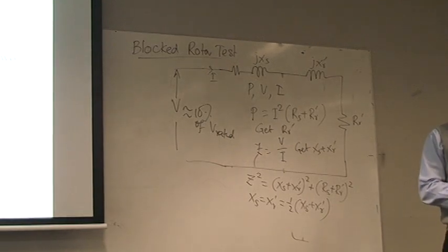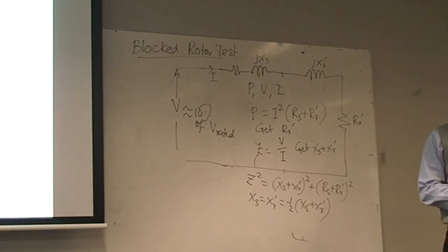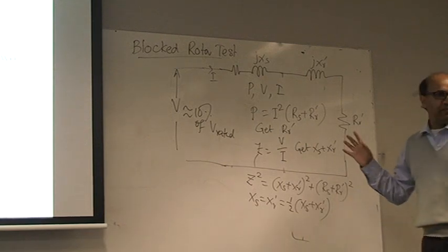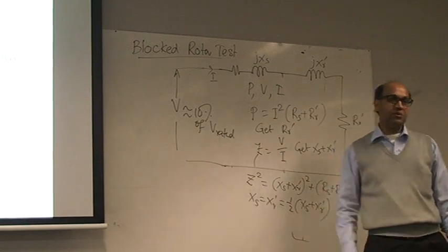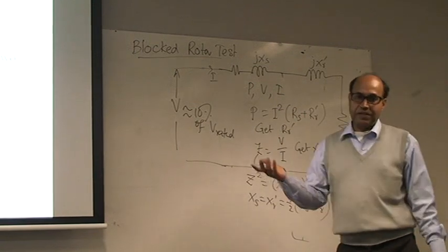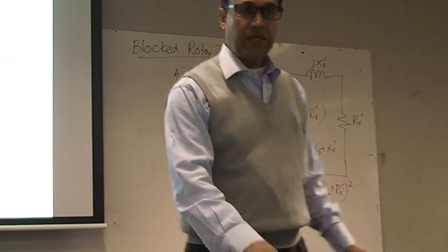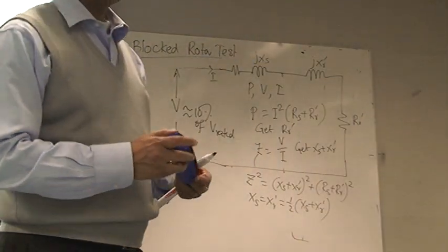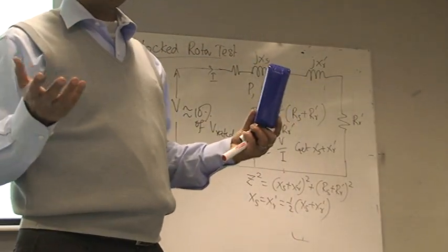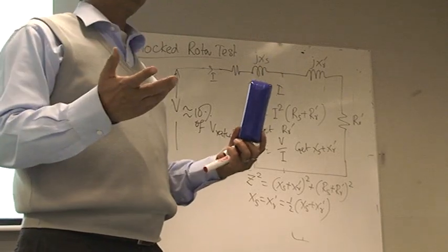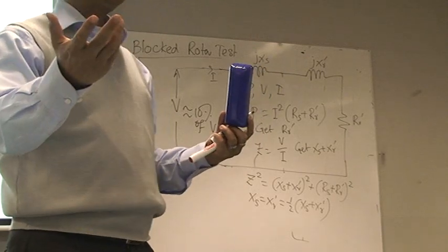Yeah, because I was just thinking, if we're only doing 10% of the rated voltage, if it's a very high voltage motor, it's still a fairly large resistance and impedance we're ignoring. So there will be some. So it's a percent accuracy. Yes, you will have that, but at the end of the day, what exactly you are going to get is the approximate circuit parameters, which will be useful to analyze your induction motor.